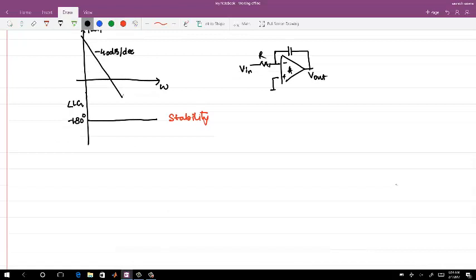So now with a changed loop filter for stability reasons, earlier I had ICP going to C1. Now this changes to ICP, R1 and C1. So this node is still the control voltage node.